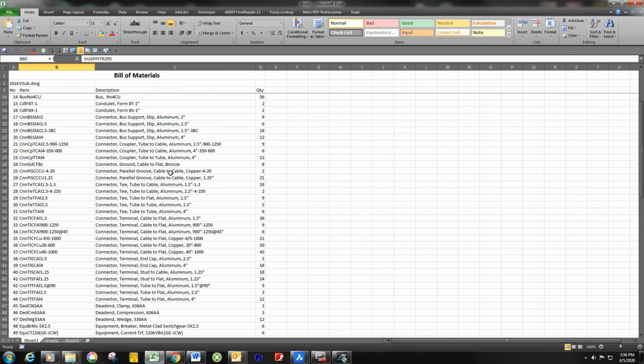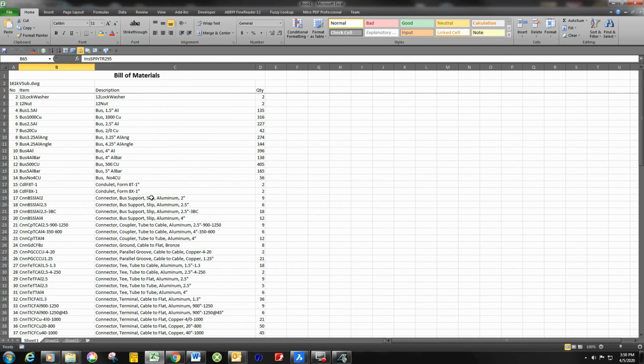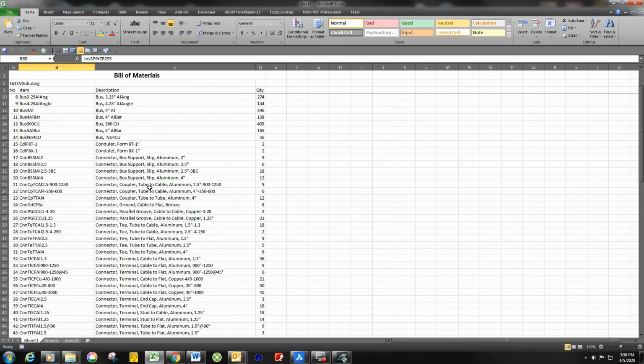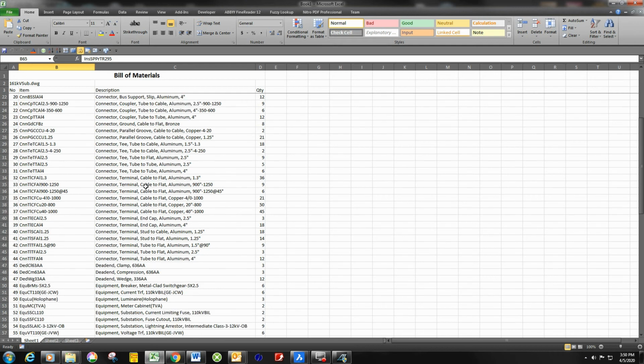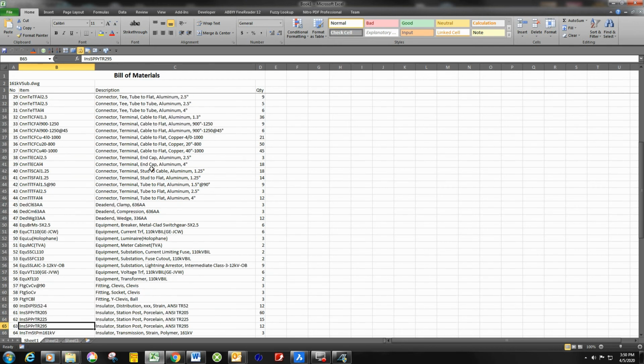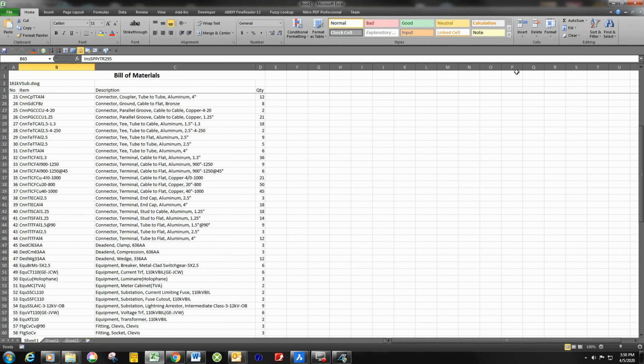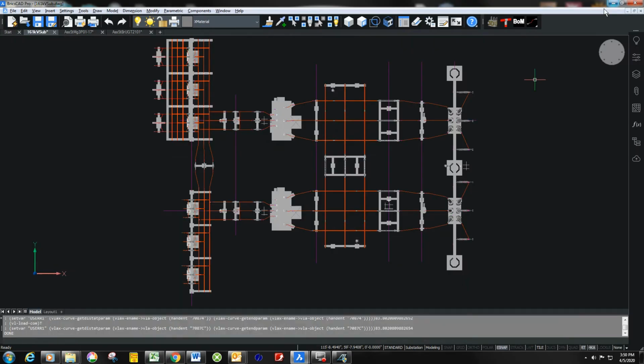because you get down to the end of the job and find out you're short one or two connectors, or some feet of bus that may take 6 weeks for delivery, or some of these connectors are actually cast on demand. You may find yourself with a serious delay in the completion of your substation. So that's for your bill of materials.